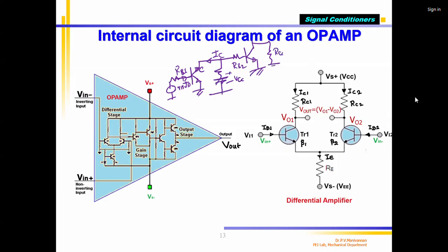Again, supply voltage. Then take the output, give it to one more stage. Like this, I give the input here because of this IB. This has a beta of, for example, 100. All the transistors have beta equal to 100. You take it, correct? I say a 3-stage common emitter amplifier, connected like this, with supply voltage. This is my RC3. This is RB3, correct? So finally take the output. This is my V0.